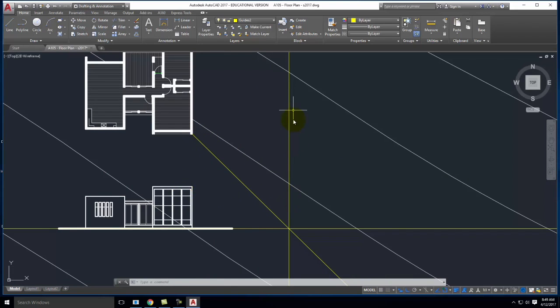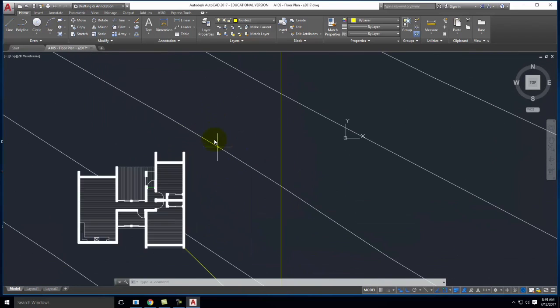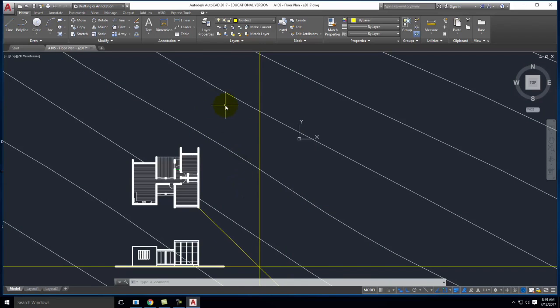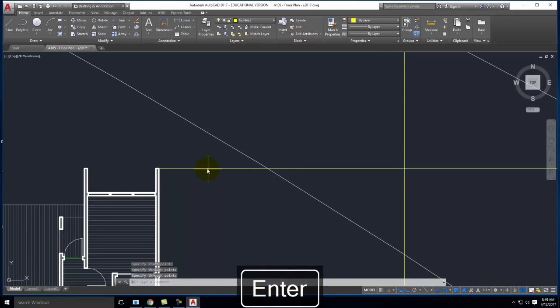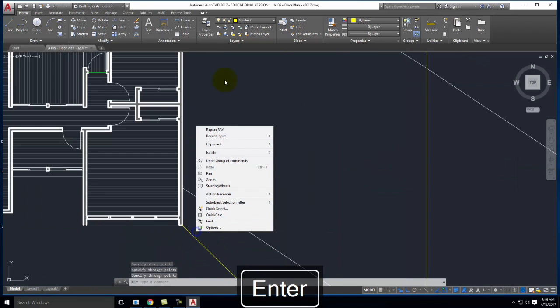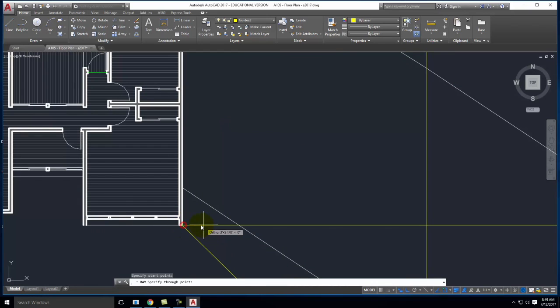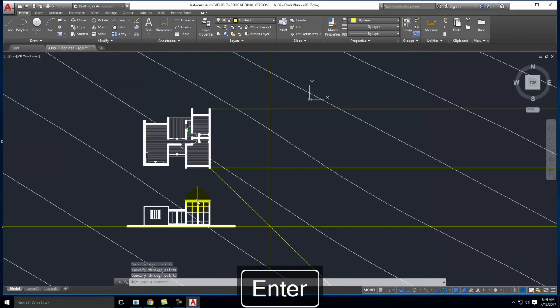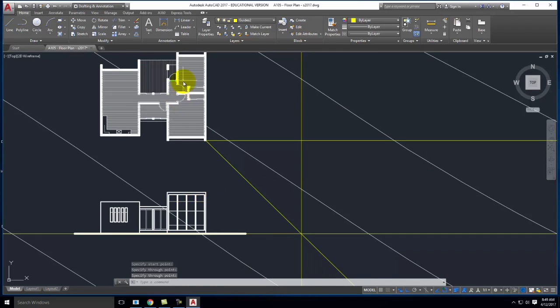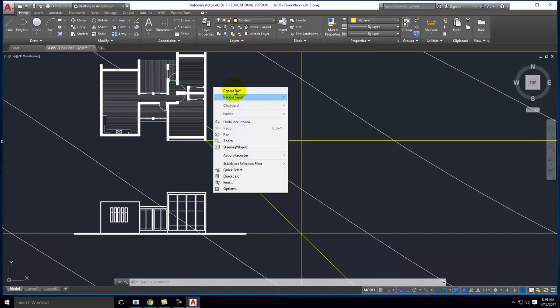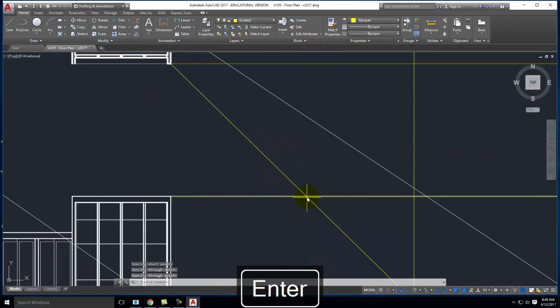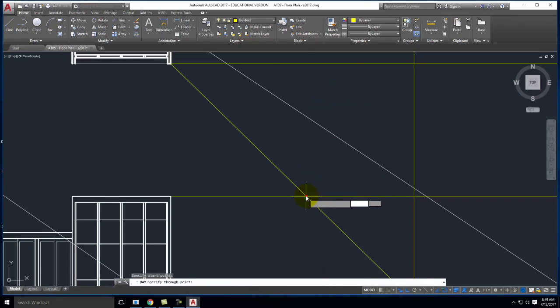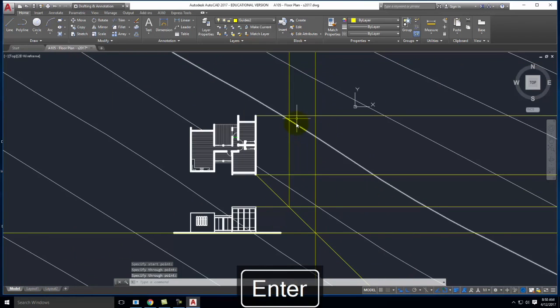So across this 45-degree line, right, I can start to draw on the side here. So let me go ahead and do array. And we'll start, just like I did before, with the major corners of the building. There's one. There's the second one. And now I need the height of this building, or this piece of the building. So I can pull that right there to the 45-degree line right here, going up. And I've now created the box that represents the outer part of my building.